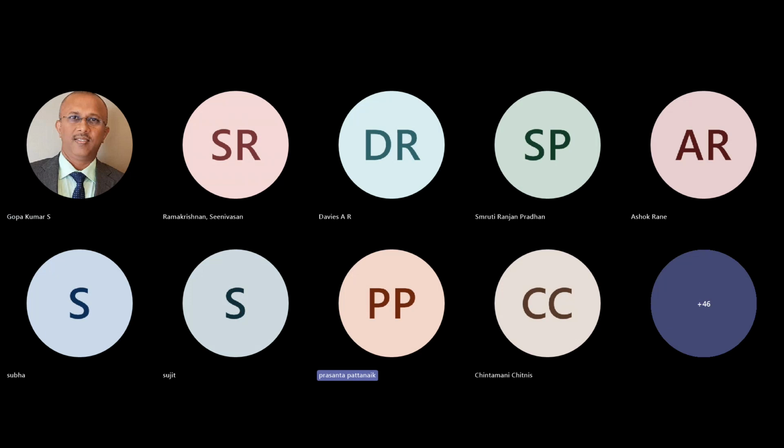Okay. Actually, Smriti, I want to add one more point, basically the kind of earthing conductor where the current returns. In the initial days, we had an earthing conductor of a particular specification. In present days, faults are happening in a different way because they are not, I can say, disciplined faults. They are nuisance, indisciplined faults, containing harmonic currents and all. So the quantum of current expected is becoming more compared to the previous time, when there were resistive loads and all.